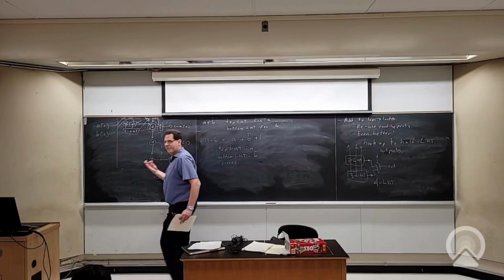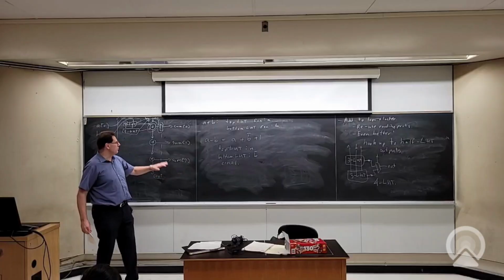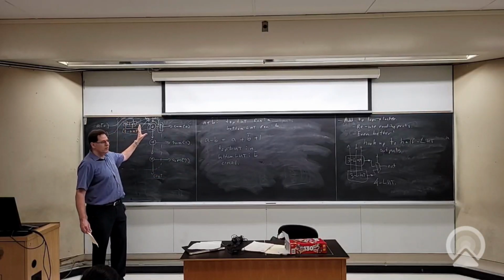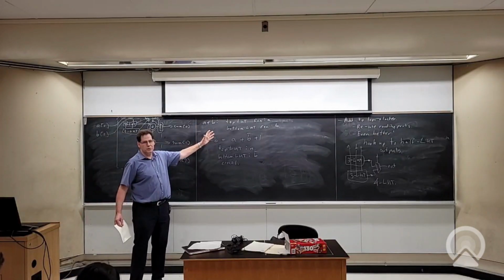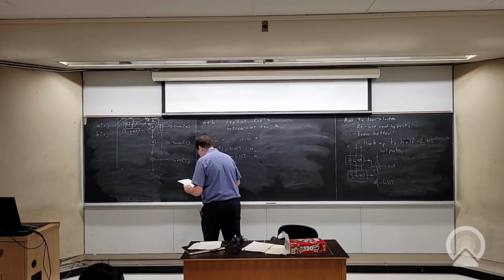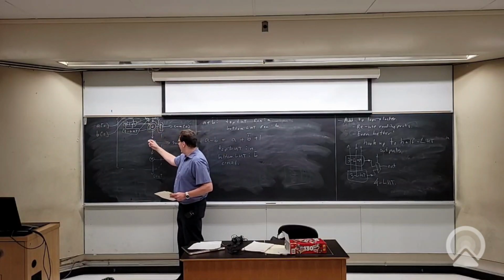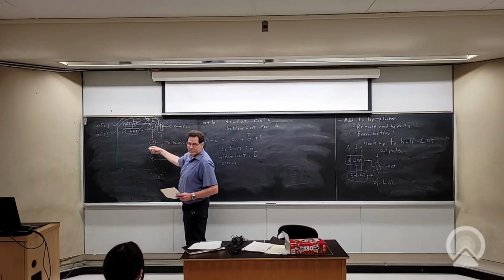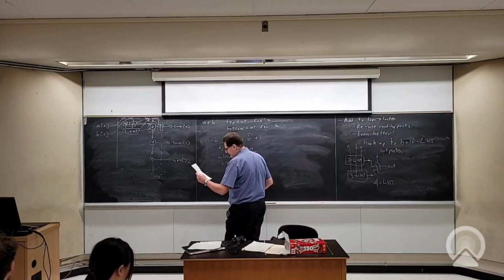But I can do more. Okay, so clearly maybe there was some logic in front of this. I can capture that in these small LUTs, so maybe get some more benefit out of them. But I can even see that already they've given me the ability to do subtraction. Okay, so how fast is this? This is all hardened logic. So a few gates, no programmability, right? Just wired together. So it's pretty fast.